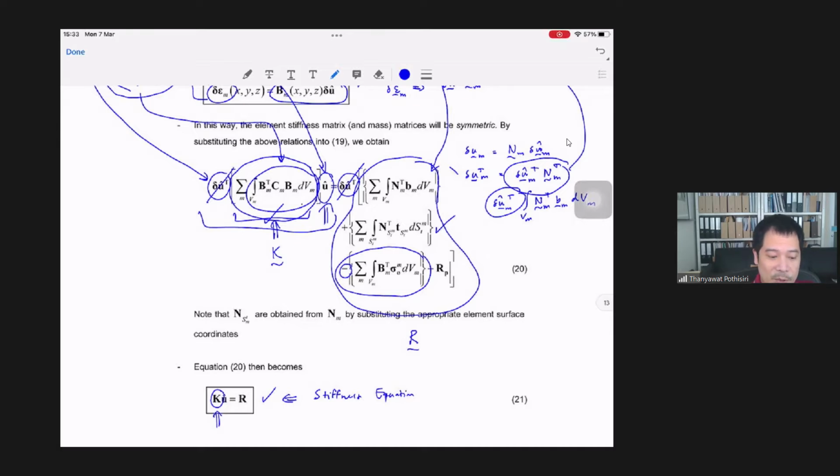So you can also construct this stiffness matrix, because it's basically how you compute the internal virtual work for each element, and then somehow combine them together to represent the whole structure. So you can obtain another matrix for the entire structure, and write your equation in the stiffness equation form, which you are already used to.